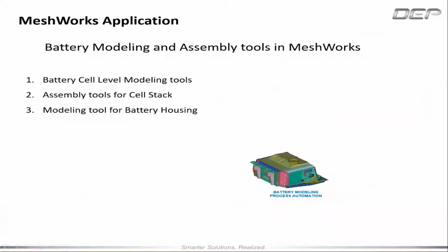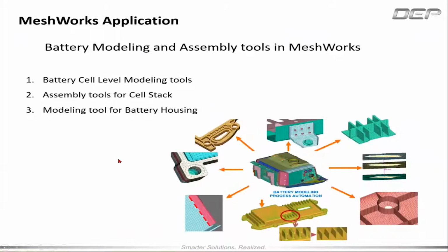So moving on to the next one, this is where we will be looking into battery modeling. When it comes to battery modeling, here we can see the parts consist of a variety of modeling techniques. We have shell mesh, we have tetra mesh models, we have hexa mesh models, and we also have to do the connectivity. The connectivity being seam welds, 1D bolts, 3D bolts, etc. And we as engineers know such models are really complicated and consume a lot of time. We will now see how we can use MeshWorks to very efficiently create such assemblies.